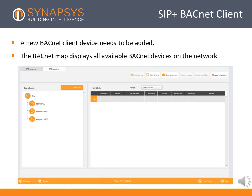Once the BACnet router has been configured, the client device can be created in the Define Points page. Open the BACnet Client tab at the top left of the page and add a new client using the Add Device button. The new device needs a unique instance number and label. There are also optional settings to give a description and location to the device. This will make it easier to identify on a network of other devices.